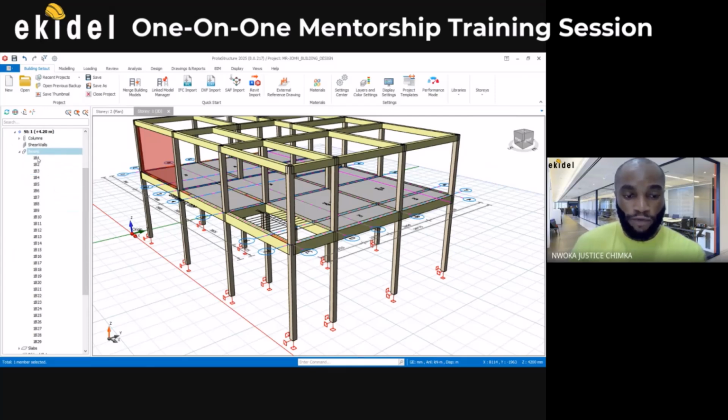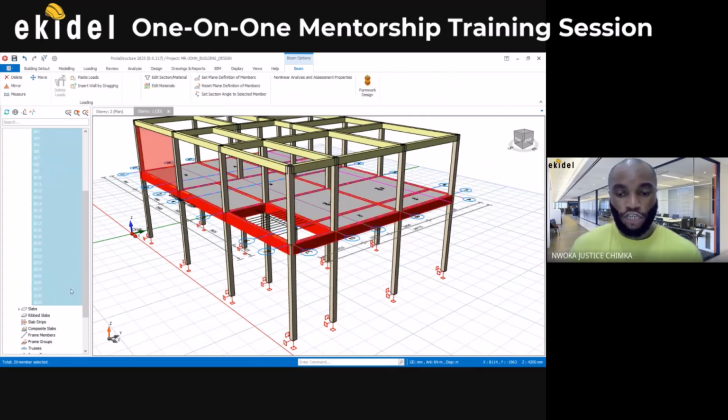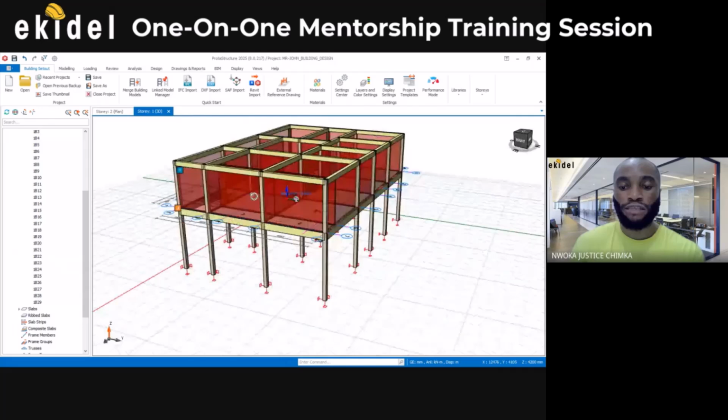Then click on the first beam, hold your shift key, and click on the last beam. It will pick all the beams on that level. Then come out here, right click. You will see paste loads, right? Click on the paste loads. You can see there, all the load is now pasted here.